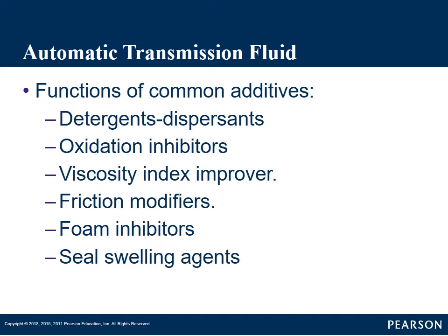Oxidation inhibitors. This reduces oxidation and decomposition of the fluid. In other words, it helps that fluid last longer. It doesn't break down. It doesn't start building varnish or sludge up on the different metals in the transmission.